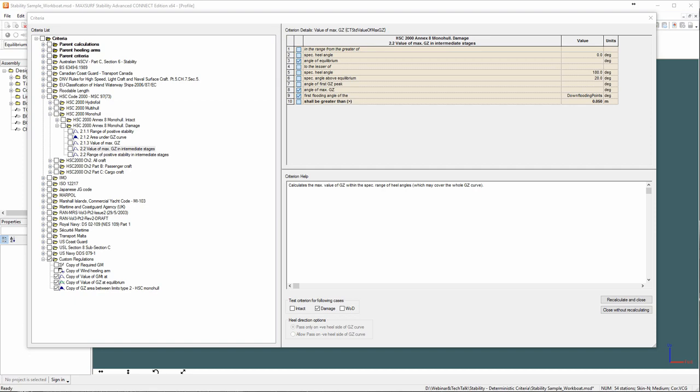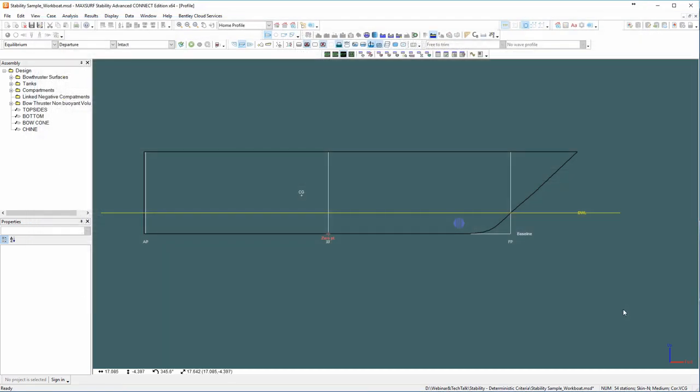In these cases, we specify a percentage filling in the tanks that represents how flooded that tank is at that point in time. So let me pull up a damaged tank. So this is a standard damage scenario. MAXSURF uses a lost buoyancy method when dealing with damaged tanks. There is an alternative system that is not implemented in MAXSURF, that is the added weight method.